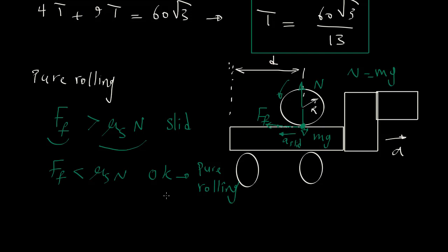So you might say that that adds one more unknown to our set of equations, and we wouldn't be able to solve the problem. But the key here is that we add one unknown to the unknowns, but we also get rid of one of the unknowns. If the disk is sliding, the value of the friction force for the kinetic friction is known.